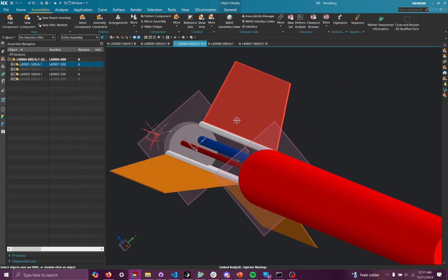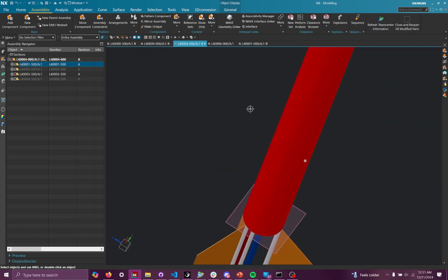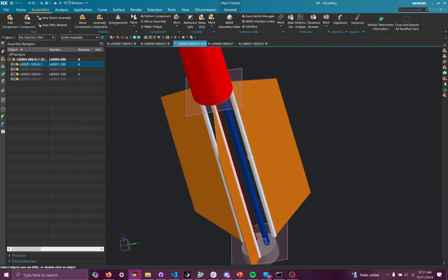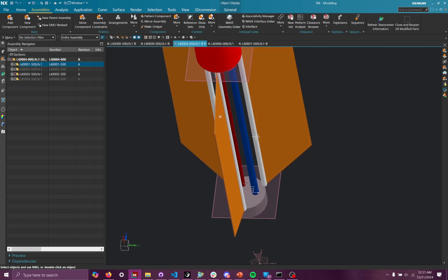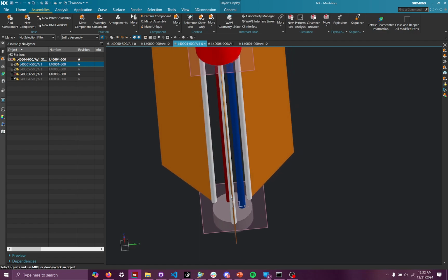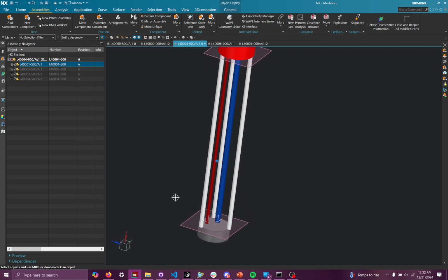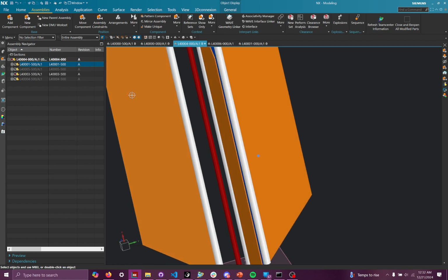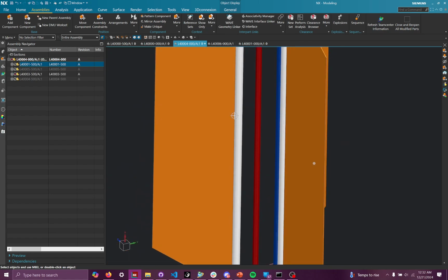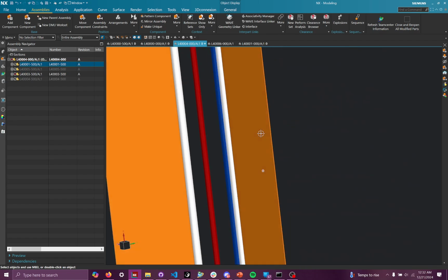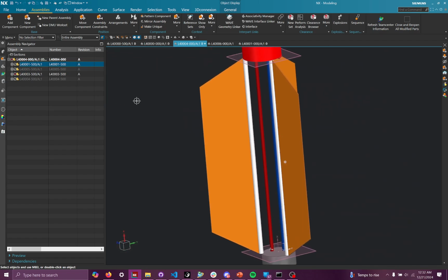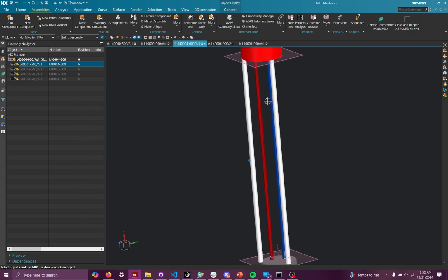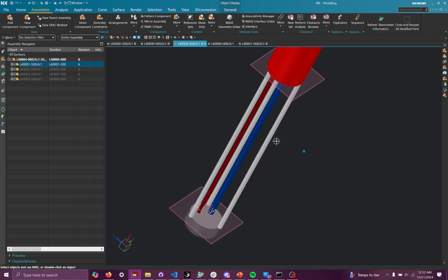There could be a case where you do, but I don't think you'll ever need to deal with the fins if you're working on the lower plumbing system. So I didn't include that when I wave geometry linked in stuff, and I just did the struts. So I don't have to work around these big orange blocks in my way, because that'll get a little bit annoying. Again, simplify as much as you can to make it easier on you to understand what's going on.